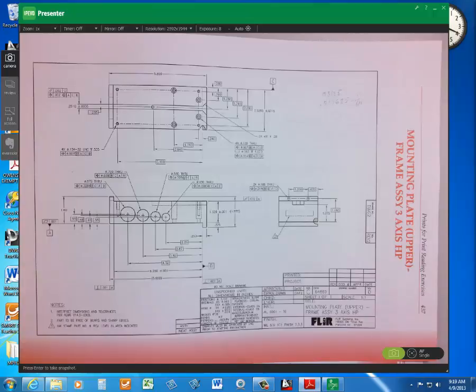If it's very deep, then it's got to be pretty large so that you can wiggle it into position and get it off, in case it gets stuck. Those kinds of things have to be accounted for. But there is a standard socket head measurement for a given socket head screw size.